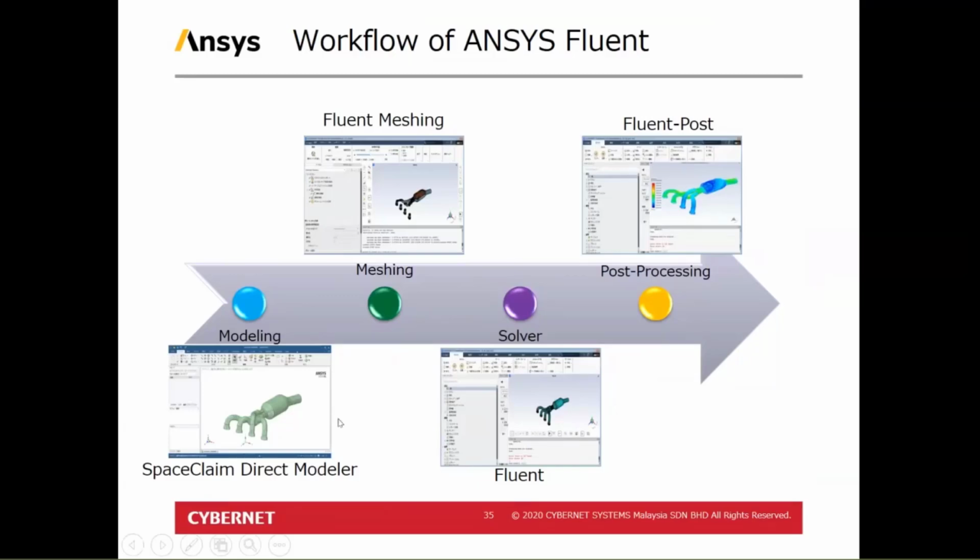After you prepare the CAD data, you have to make the mesh. The meshing process is very important because the mesh decides the simulation cost, quality, and the stability of calculation. After you prepare the mesh, you move to the solver setting, and you start the calculation.